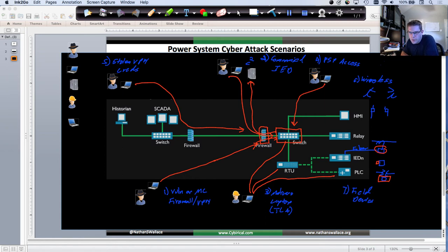When you're looking at all this data coming in, what happens if all that's malicious? Well, this IED is really only going to operate with the information it's receiving, so it could potentially cause more harm or more damage, right? Same thing, if this status being looked at is sourced from this sensor right here, then this operator could be tricked into doing something he's not supposed to be doing. So there are different ways to do this.